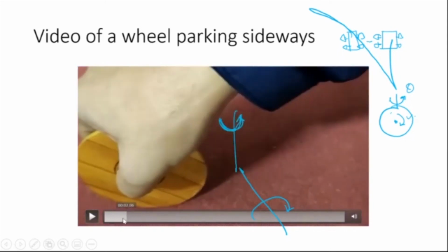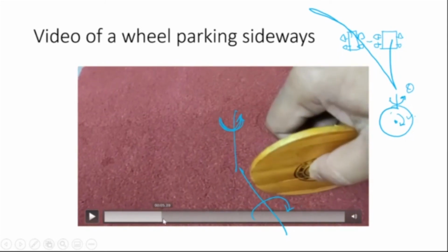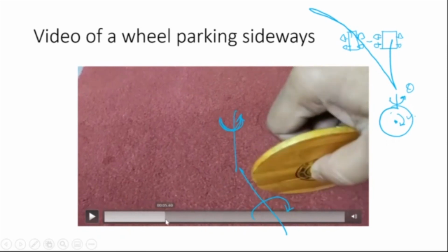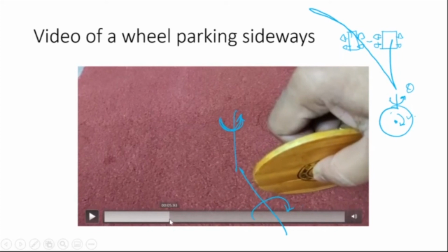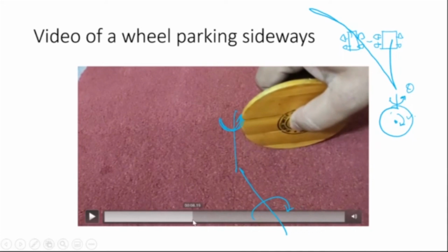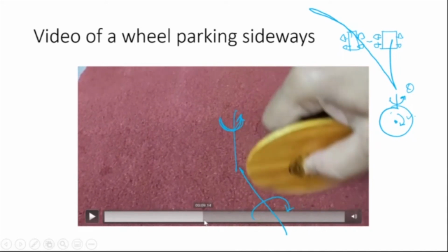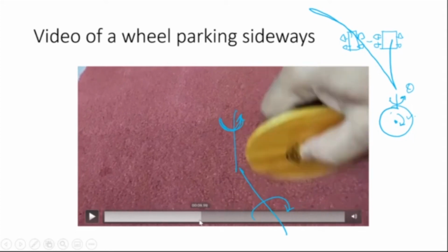So it has two motions. The one motion is it can go front and back. You can see that. The number two is it can twist about its axis. This is what it can do. Now, the wheel cannot go sideways. See, the wheel cannot go sideways. This sideways motion is not possible because of that single non-holonomic constraint. Because of this non-holonomic velocity constraint, this robot cannot go sideways.